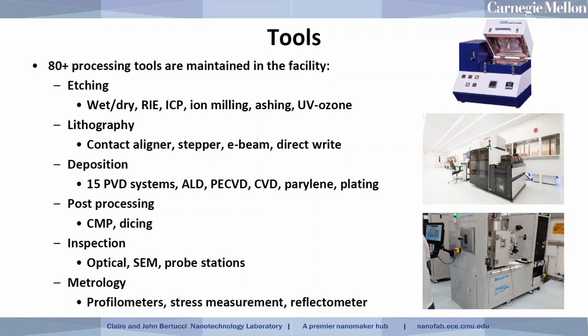Deposition is a real strength of the lab, so we have 15 PVD systems, including sputtering, evaporation, ALD, PECVD, CVD, parylene deposition, plating, so we can really do a lot of things with deposition. Our post-processing is mostly outside of the lab, which includes CMP and dicing. We have various inspection stations and characterization inside the lab: microscopes, SEM, probe stations.